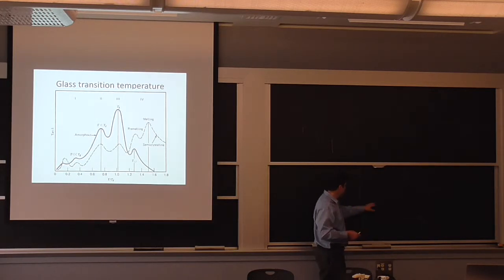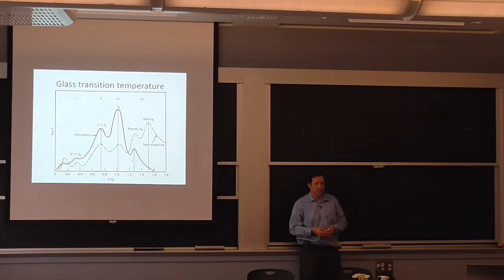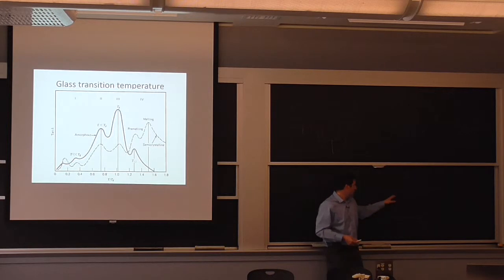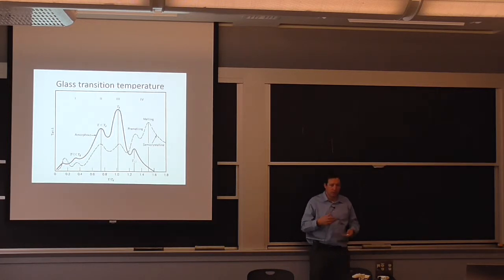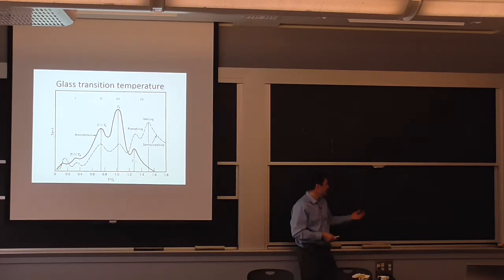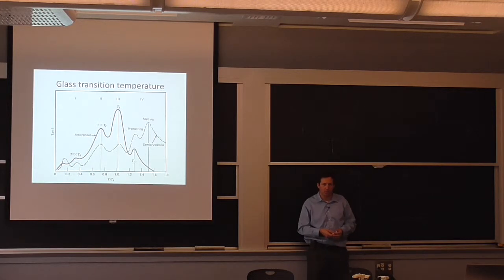So if you are very, very cold, you're a little bit like glass or a rigid polymer that won't have really much time dependency because there's no way for the molecular chains to move. But as you get closer to this temperature is where you start seeing the visco process, where if you give time, then all of a sudden everything becomes possible. So this is, I think, the more physics-based interpretation of the glass transition temperature.